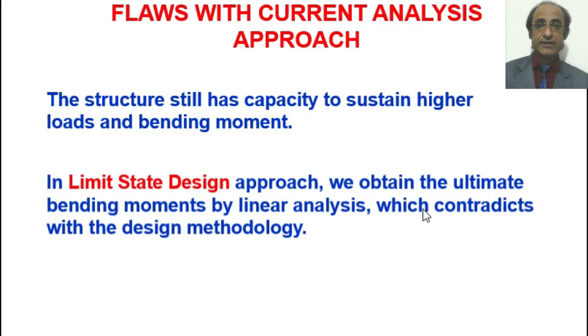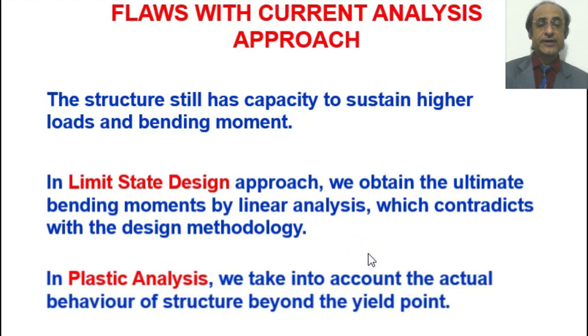Basically, we do linearly elastic analysis, and whatever the moments are, we multiply them by a load factor, and we assume that these are the moments corresponding to the ultimate state. So this introduces a kind of contradiction, in the sense that we are doing very rigorous design, but for analysis we are lagging behind. So plastic analysis fills this gap.